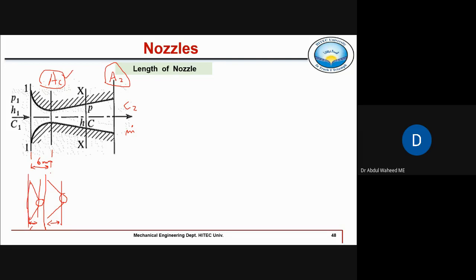एक्सक्यूज मी सर। जी। सर फ्लूइड के अंदर हमने पढ़ा है कि जो बाउंड्री की वॉल्स होती है, वहां पर जो वेलोसिटी है वो बिल्कुल जीरो होती है, और ऊपर जाते जाते वो वेलोसिटी इंक्रीज होना शुरू हो जाती है। फिर मिड के अंदर एक लाइन आती है जहाँ पे वेलोसिटी मैक्सिमम हो जाती है। लेकिन ऊपर वाली सरफेस और नीचे वाली सरफेस जाके मिलती हैं, उनको थोड़ा एरिया चाहिए होता है, फिर वो एक पैराबोलिक शेप बनाती हैं वेलोसिटी, और वो कॉन्टिन्यूस हो जाती है। तो सर अगर 6 mm रखेंगे तो ये तो बहुत स्मॉल होगा, इस तरह तो उसकी शेप प्रॉपर बन ही नहीं सकेगी।